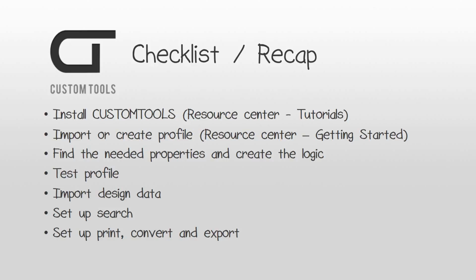That is either look at the assembly, because then you have quite a bit of properties. You definitely want to have mostly all of the properties you have in your assembly and your part files, but definitely have a look at your drawing templates, because in there you can see exactly what the drawing is linked to, and that is really simple to just copy those into your CustomTools profile.